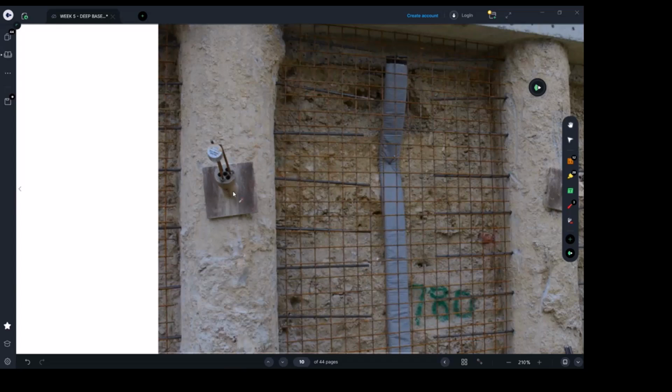So first of all, they're going to have, say, 100 diameter holes with special equipment. They're going to drill through the pile and drill 6 meters to the back in the soil. They're going to inject cables with a special dead end, like an onion, to get anchored at the far end.